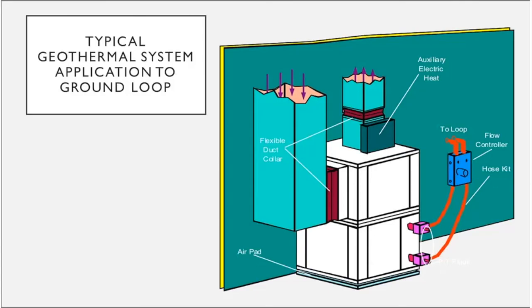But I will take that opportunity to say that we can merge the two. So you can have a hybrid geothermal system as well. In this slide, we would actually decouple this heat pump section on the bottom from the air handling section here, and then we would use a furnace. So we could use a furnace to do either LP or natural gas as our backup, and you can even select a balance point in the design of the system to where if you wanted, for example, at 20 degrees Fahrenheit, you wanted the gas side to kick on, absolutely. We can do that, no problem.